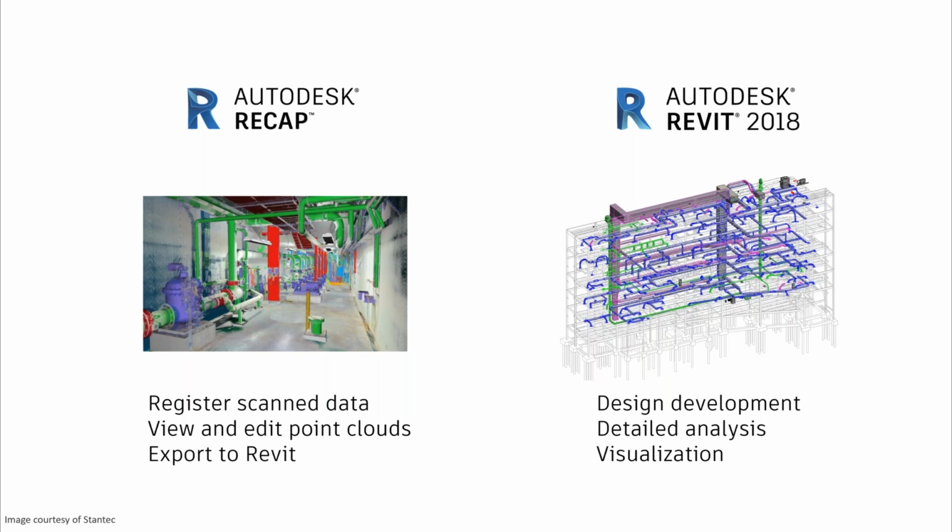For example, when you're scanning, a person might be walking here and there on the site, so everything gets captured. When you want to take that point cloud data into the design, you want to do some cleaning. You can clear out the unnecessary data in the Recap software, and take it to Revit for the design development.